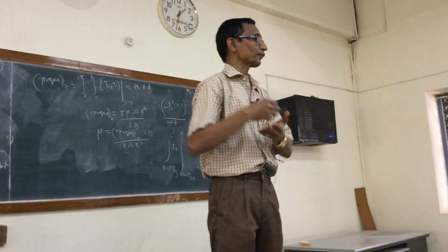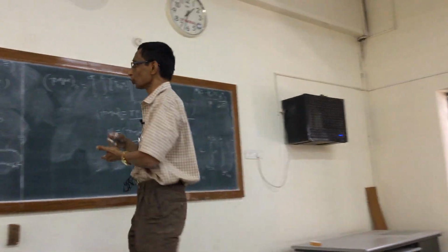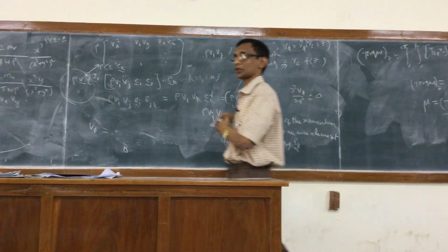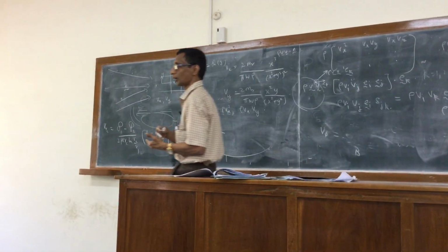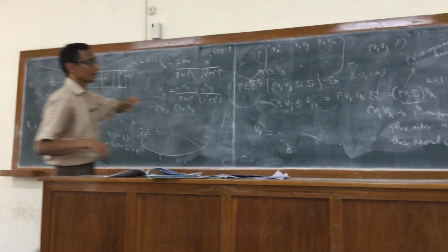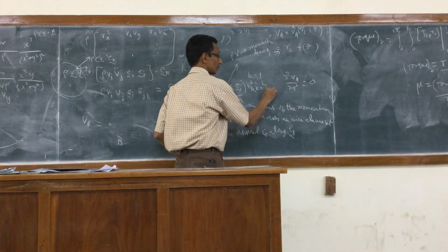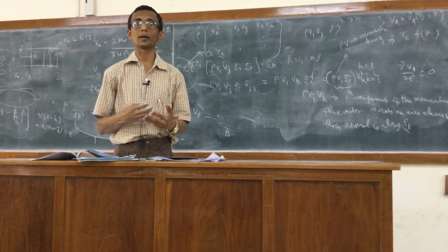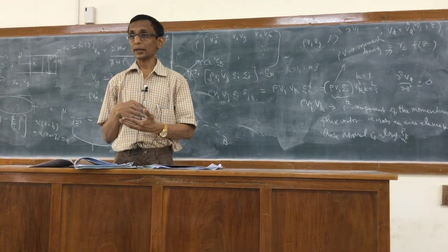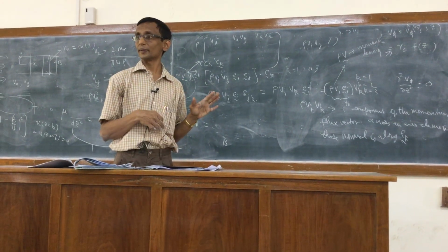That would be rho B1 B1, rho B2 B1 and rho B3 B1. So I get an interpretation for three of the elements of the momentum flux tensor. By considering k equal to 1, 2 and 3, I can give an interpretation to each one of the 9 elements of the momentum flux tensor.